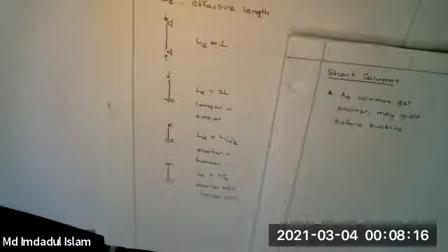So it's reasonable to regard yielding as a type of failure. And so when they get short, these columns or beams, if they're horizontal, may start to yield, and if you cyclically yield them, then they fatigue from that. So it becomes the dominant failure mode. When you buckle them, you can get these big stresses again, and so you can start yielding them too. Okay.